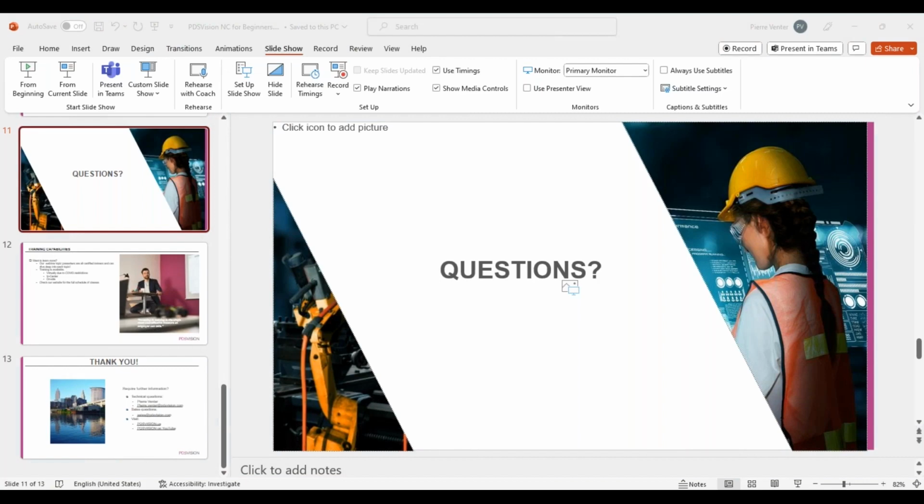Okay, so we have a question on how Creo will handle model errors, like if there are gaps and things like that. I assume you're talking about surface models. Surface models are a little bit trickier. If it's a bad surface model and there are gaps outside of the accuracy, Creo is going to see those gaps and it might try to push a tool in there, but it depends on the accuracy. So you can play around with that and fix those gap errors.